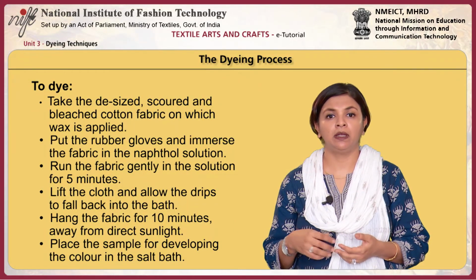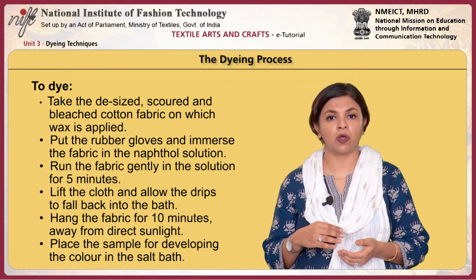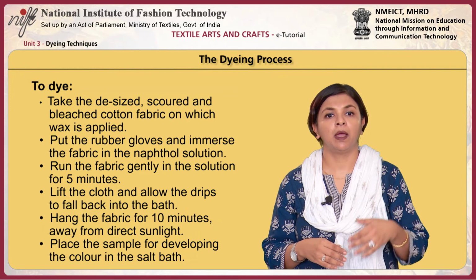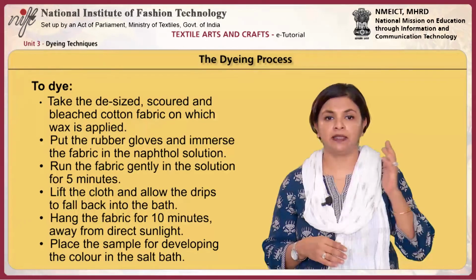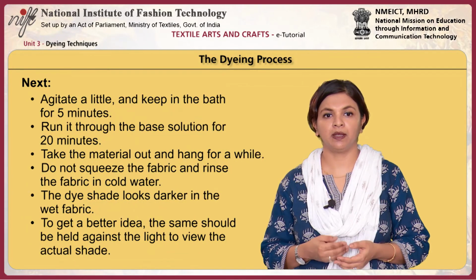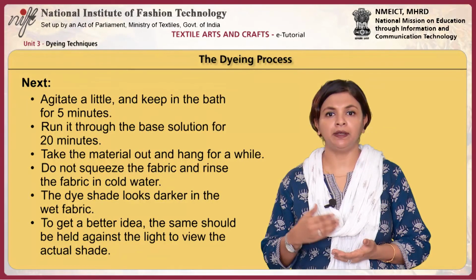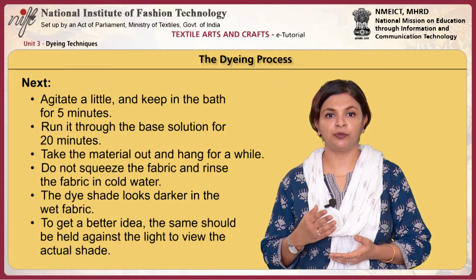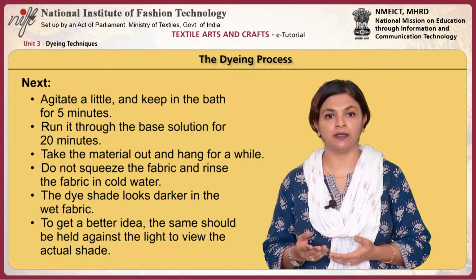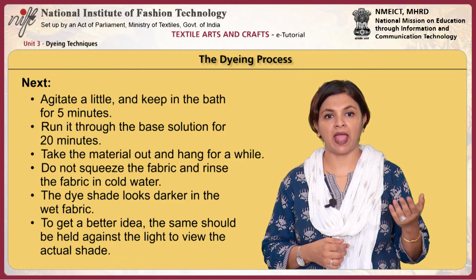Any naphthol that drips into the diazo salt bath exhausts it. Place the sample for developing the color in the salt bath. Next, agitate a little and keep it in the bath for 5 minutes. Run it through the base solution for 20 minutes. Take the material out and hang for a while.